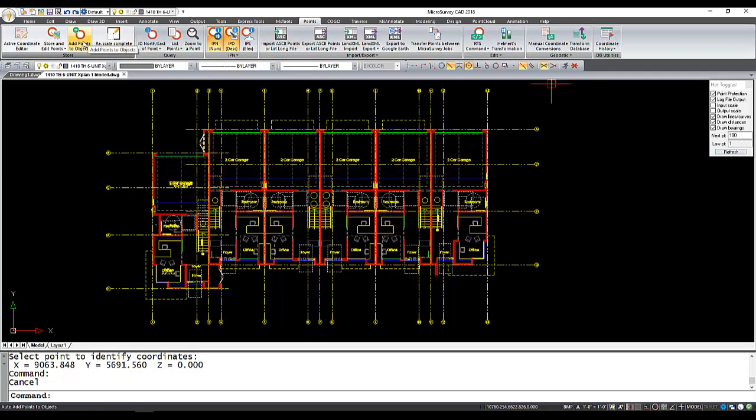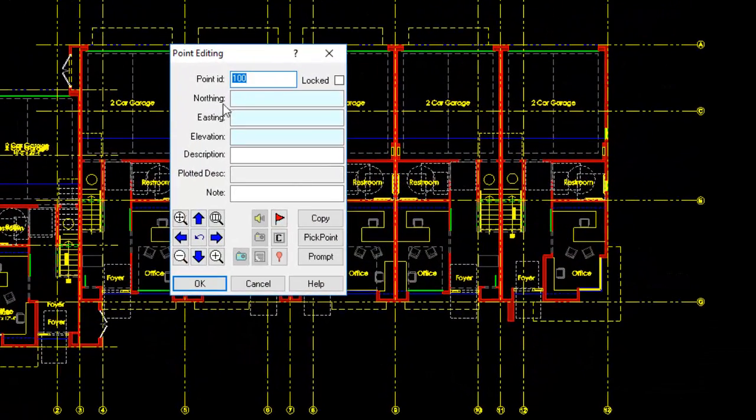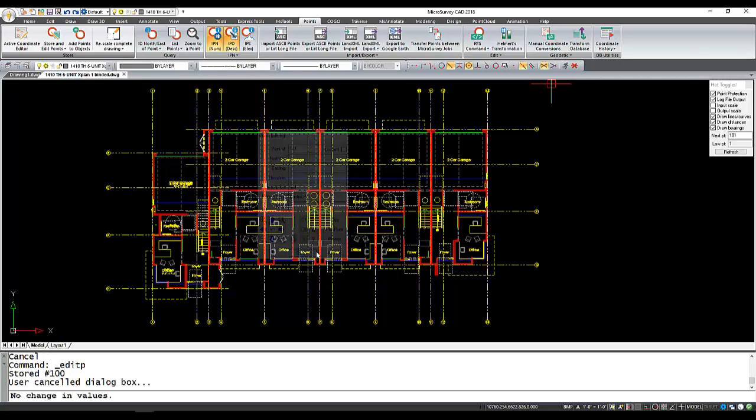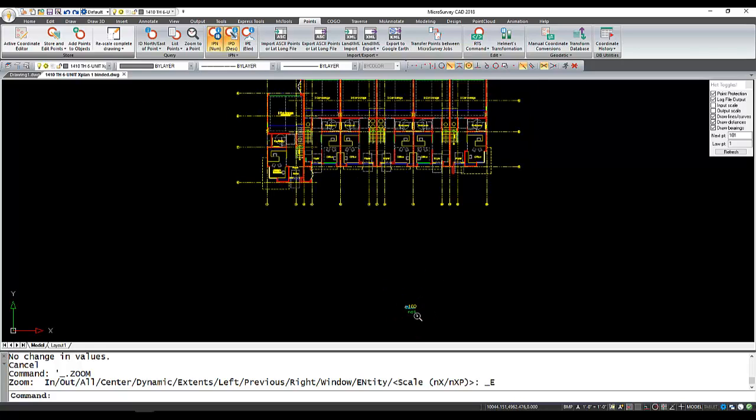And then we're going to go over to Store and Edit Points. And this will prompt me to manually input some coordinates. So I could input 5,000, 10,000, leave the elevation at 0, and this is a nail. And notice how it recognizes the field code I'm typing in, and the automap is going to insert a description of control point to it. Say OK to that, and so if I zoom to extents, I'll just cancel this. Then I'll find that that point has been plotted down here.